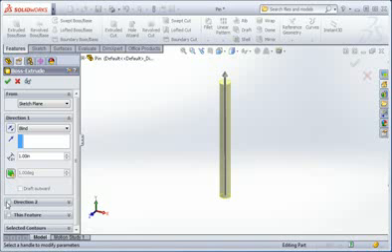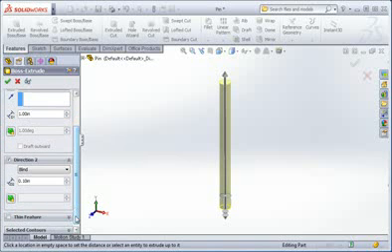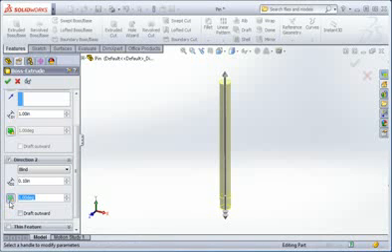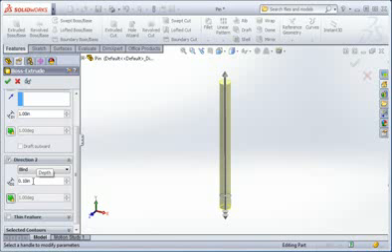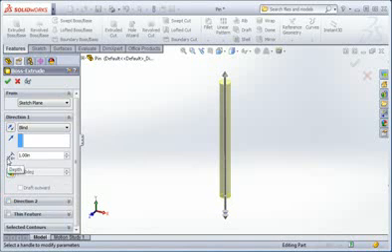Another thing you can do is add a second direction to the operation. Direction 2 always points 180 degrees away from direction 1. So this option is like making an independent extrusion in the opposite direction. It can have draft, and it can be a different length. But notice that you don't have the option of changing the direction. That's because direction 2 points in the opposite direction of direction 1. We'll talk about the other options for the Extrude command later in the course. For now, uncheck direction 2.